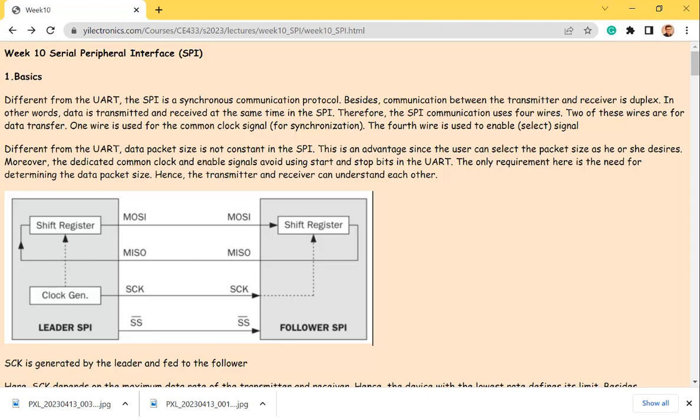So I2C has SDA, which is for data, and SCL for clock. Just two lines for I2C. It's two lines, so it's very simple to use, and also for programming. But the logic circuits inside the modules are very complicated. So whenever it's getting easier to use, the design will be more complicated.